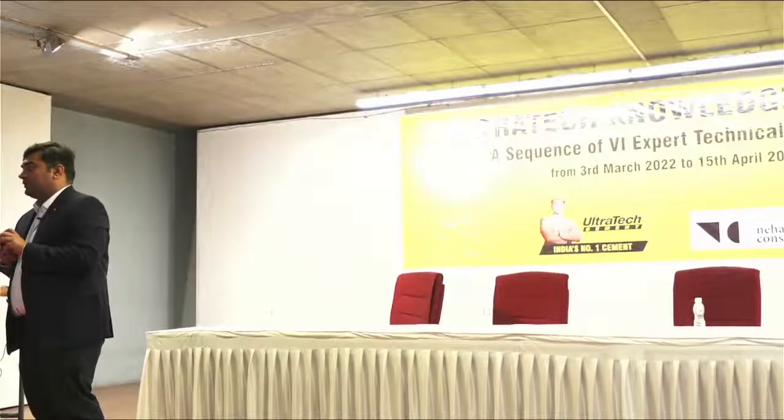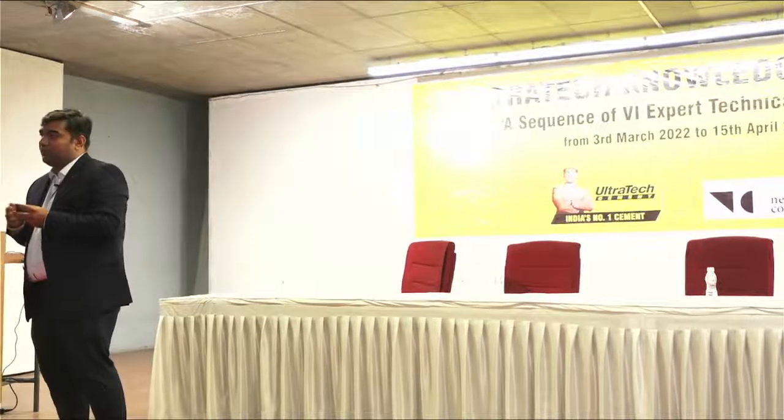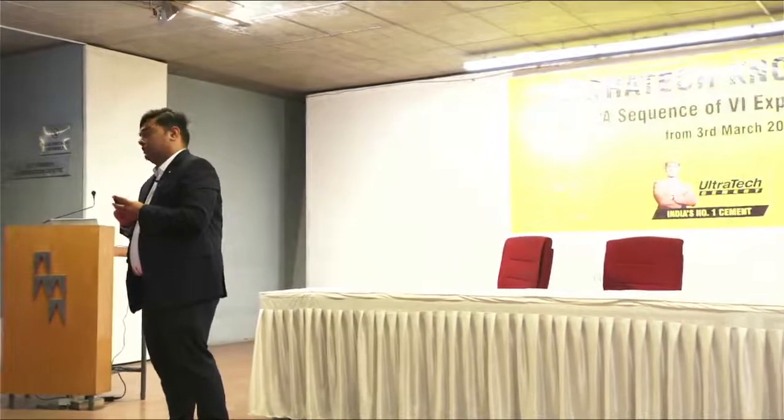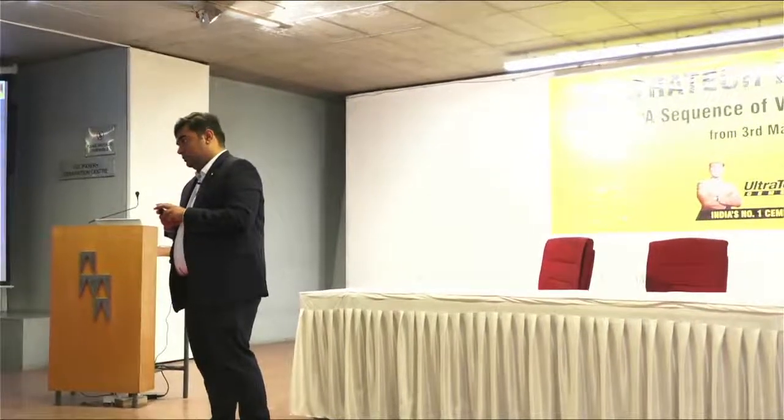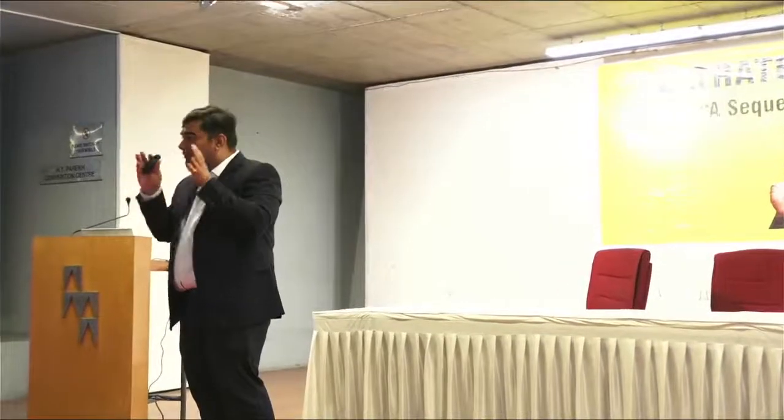No, it is not time consuming. It's time saving. You can build a single story house in just a matter of 8 hours. Right now, printing is said to be time consuming, it is said by the designers also. But it is not time consuming when you know the extrusion process and you have designed the building as well as the mix design. Why are they saying it is time consuming? Because the structural design as well as the concrete mix design is an iterating process. I mean to say that it has to take many turns before the final design is set up. That takes time, but the construction process does not.